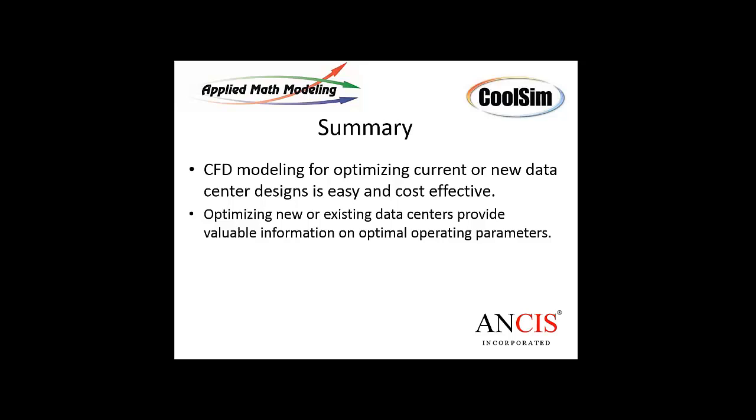I'd look there. Another question is, what's the maximum temperature a typical blade server and other IT equipment can handle for proper operation? We assume in this modeler, mostly, 20-degree deltas. The basic equation that I showed earlier, heat transfer is equal to mass flow rate times density times specific heat times delta T, shows that to reject 1 kilowatt of heat away from a server like that, you need about 156 CFM for a 20-degree assumption of rise across it.